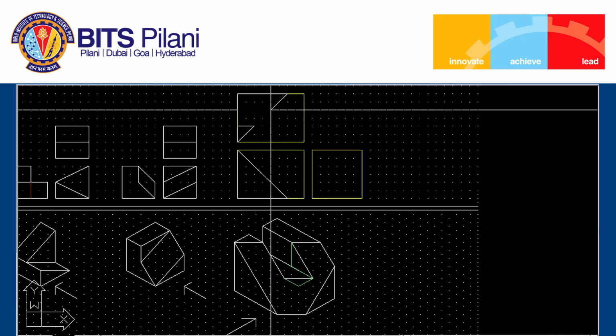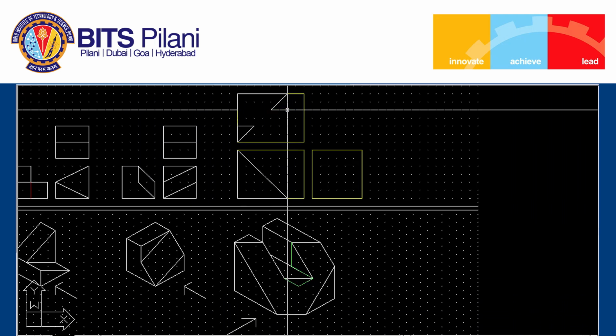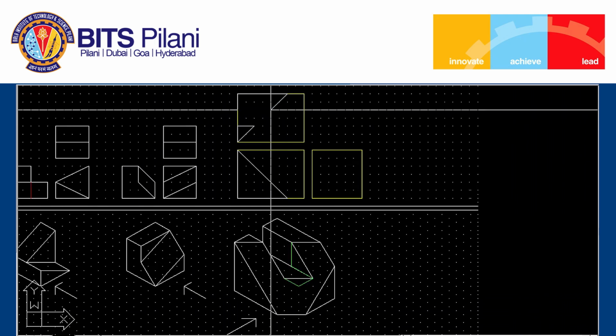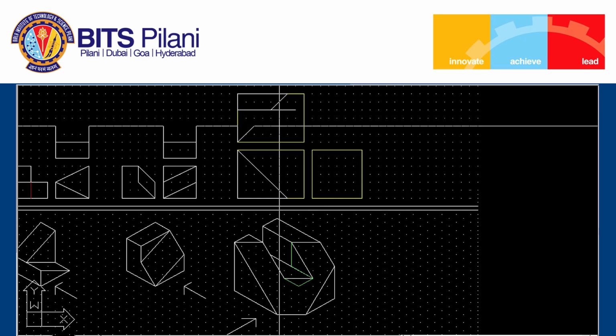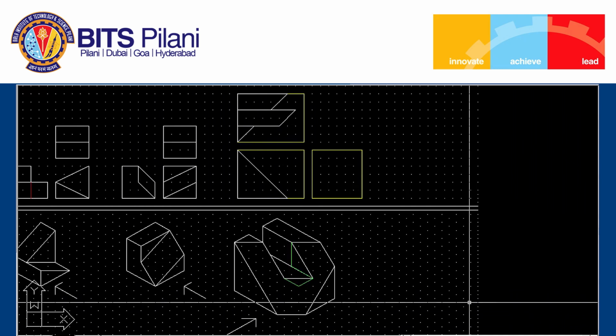So, from this point I can see the length dimension, 1 2 3. This corner will be seen in the top view, and along the depth 2 and length 2. So, the other corner is here, and then I can join. So, I can get that third principal surface. Okay. So, I have located that point in the top view.